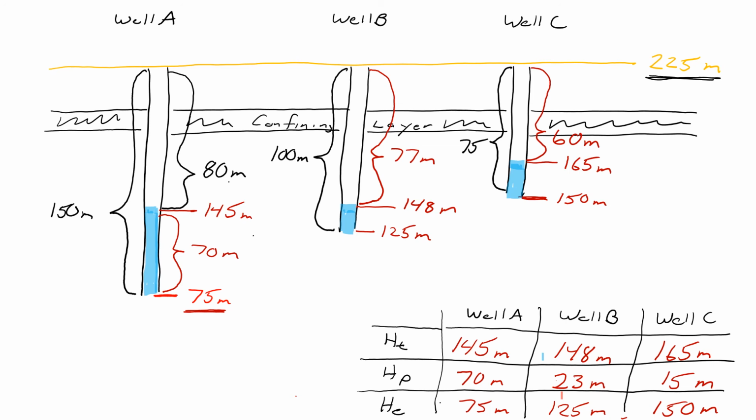But when you drop it down and hit water, because water conducts electricity, it completes the circuit. So you feed this tape down the hole, and when it hits the water, it completes the circuit, and the little battery is hooked up to a little beeper, and it makes a beep. Then you just look at your tape measure, and it says 80 meters, or 60 meters, or 70 meters. Really simple, sweet little contraption.